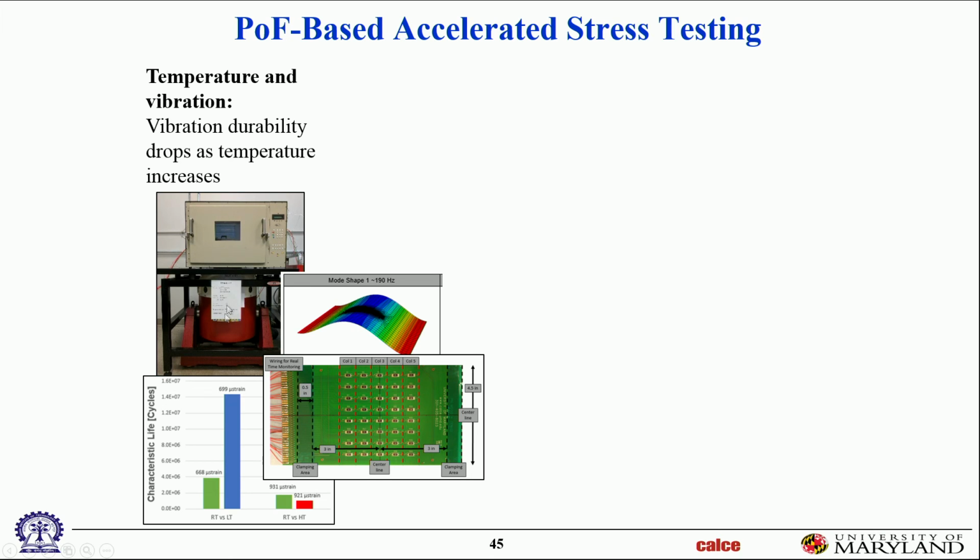So we set different temperatures in the chamber. The shaker head is inside, the specimen is inside, and it shakes it at different frequencies, different PSD profiles, different amplitudes, and we generate failures, and we build vibration fatigue models out of those.